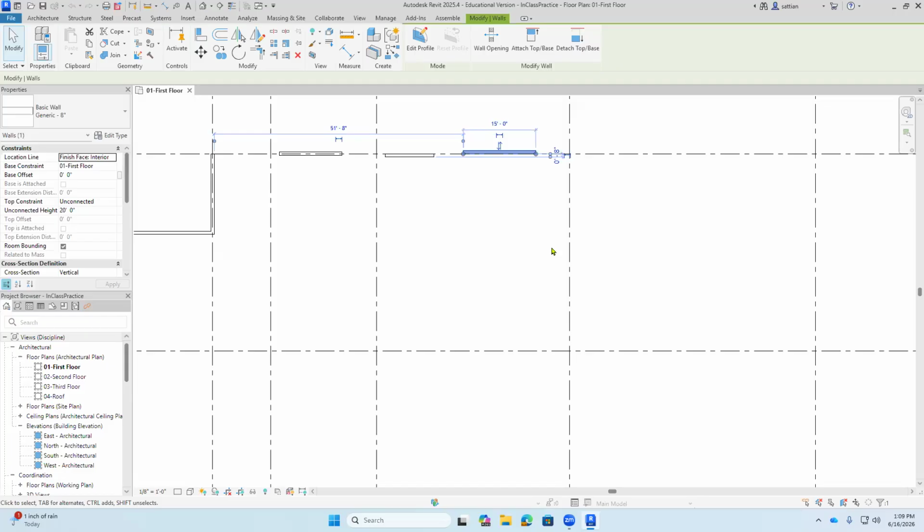On the outside, I would like a vapor barrier, air layer, thermal protection, which would be rigid insulation. And then I want an air layer and brick on the outside. On the inside, I want metal framing or wood framing, up to us. Let's say 2x6 framing, and then drywall. Does that make sense? Let's say 7/8 inch drywall.